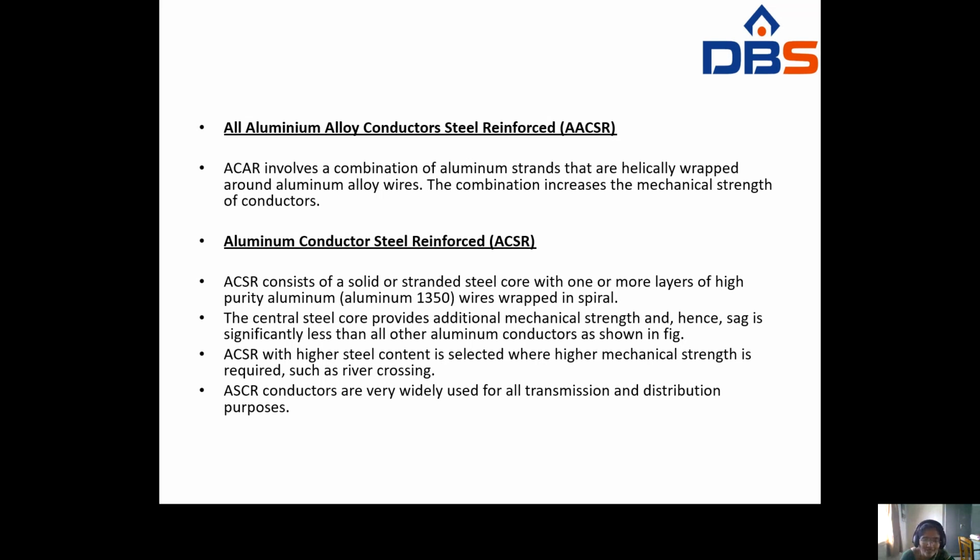ACSR with higher steel content is selected where higher mechanical strength is required, such as river crossings. So ACSR conductors are mainly used where you need higher mechanical strength, mostly in river crossings. ACSR conductors are also widely used for transmission and distribution purposes.